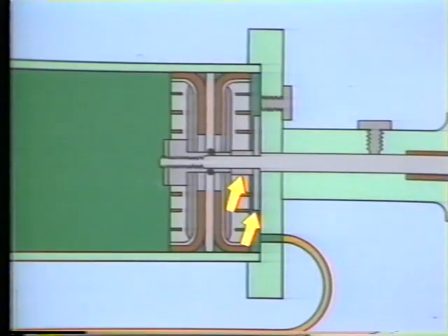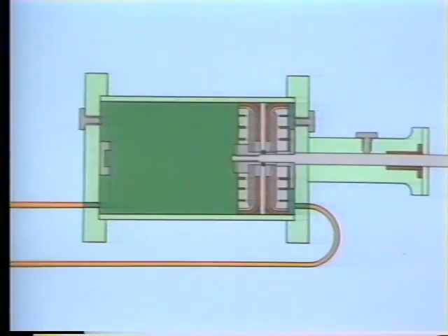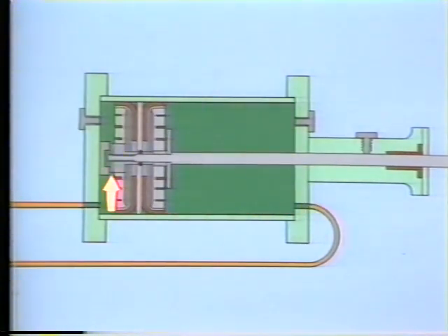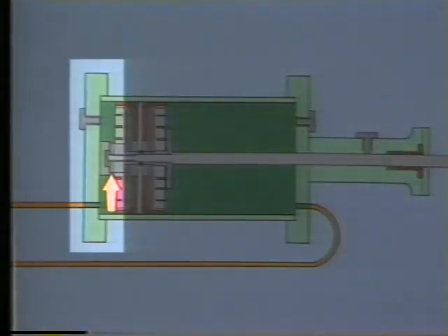Notice that the spacer and washer prevent the piston from touching the end cap. The piston can be moved to the other end of the actuator by applying air pressure through this port and venting air to atmosphere through this port. The nut on this side of the piston prevents the piston from touching the end cap on this end of the cylinder. So all of the internal parts of the pneumatic piston actuator serve one purpose: to move the piston rod in response to changes in air pressure. This produces a mechanical motion that can be used in a large variety of processes.